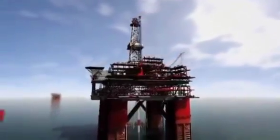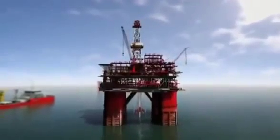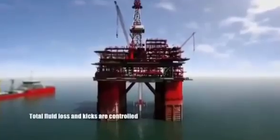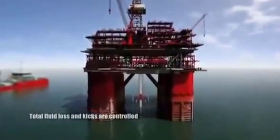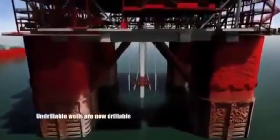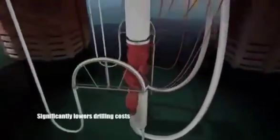Because pressurized mudcap drilling is engineered to inject all the drilling fluid, cuttings, and produced gas into the formation, total fluid loss and kicks are controlled. As a result, difficult or previously undrillable wells are now drillable. By reducing non-productive time associated with fluid loss and major gas influx, pressurized mudcap drilling significantly lowers drilling costs.